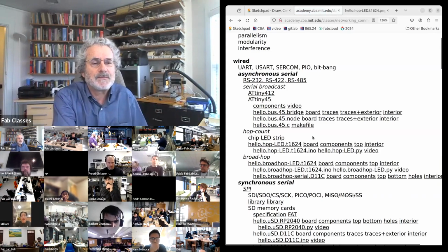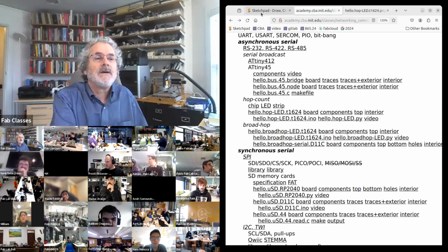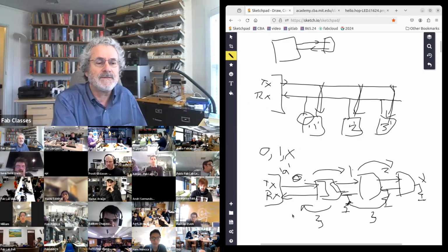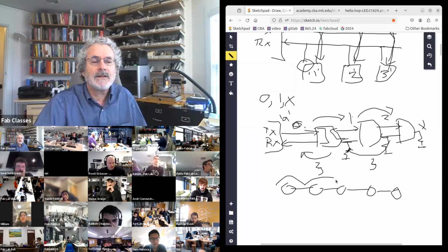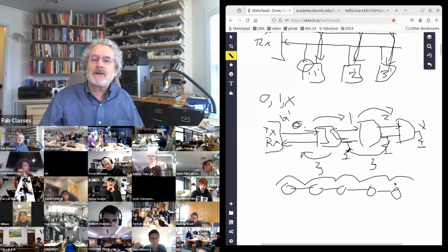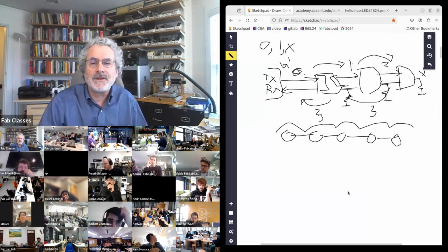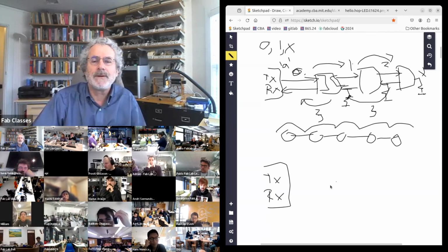Okay, so that's hop count. Then I had a project where I needed a hybrid where I didn't want to assign addresses, but in the hop count, if you have a long chain of many nodes, it can take a long time to hop a message. I had a project where I needed to get the messages out more quickly. So the third version I'm going to show you is a hybrid of these two, and it's called broad hop.